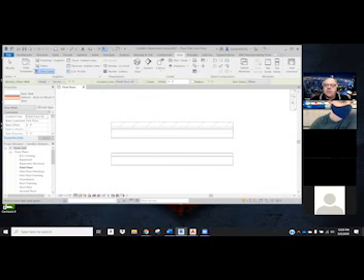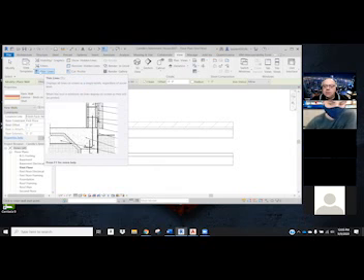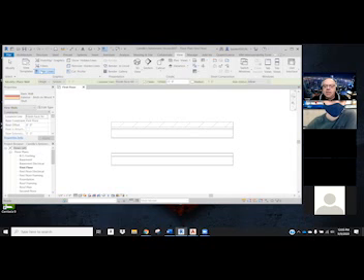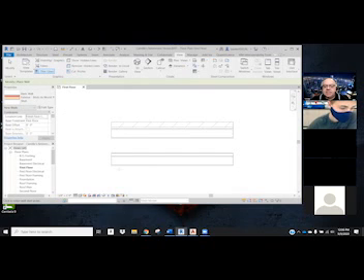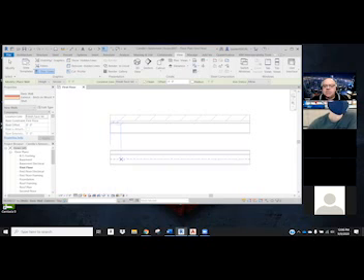Now, the other thing that's going to bother you is in the view tab, there's a thick line and a thin line. So go across the top, find view. Over on the left-hand side, there'll be thin lines. That's a toggle, meaning you can turn it off and on. Notice if I have the thick profile line, I don't get all the detail I need. But if I have the thin lines, I can see all the gypsum board layers, the sheathing layers. I can see all the components of my wall, so I get a little bit more detail to it. Okay, and hopefully that helps a little bit.